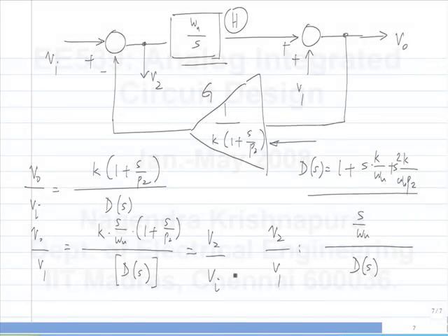So you can see that the denominator polynomial, and hence the poles and quality factor, all of these things are the same for all transfer functions, regardless of where you feed the input and where you take the output from in a feedback system. Okay, the numerator does change, so the zeros do change. So for instance, this is a